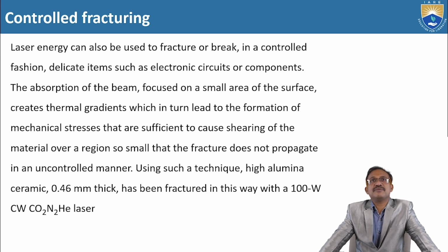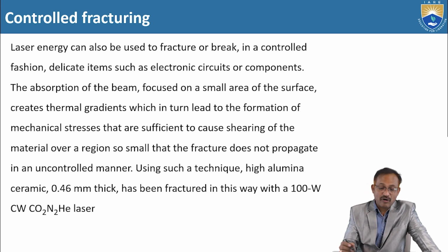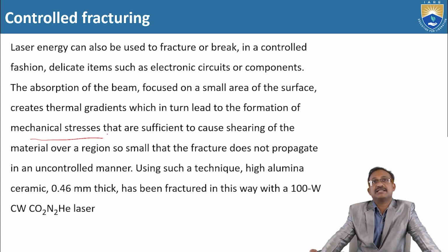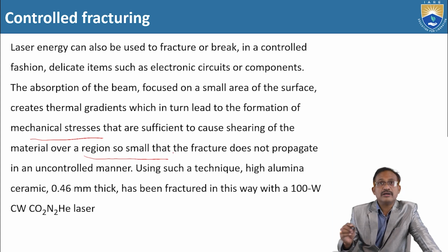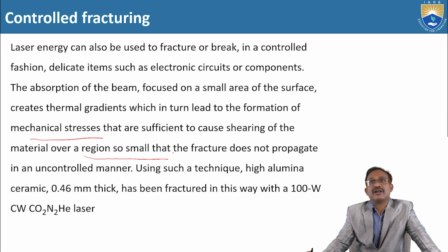The absorption of the beam focused on a small area of the surface creates thermal gradients, which in turn lead to formation of mechanical stresses that are sufficient to cause shearing of the material over a region so small that the fracture does not propagate in an uncontrolled manner.